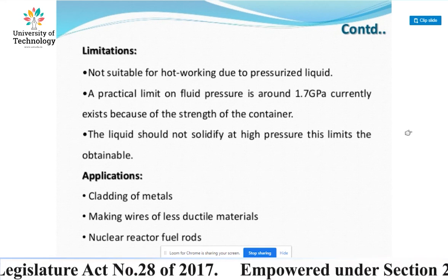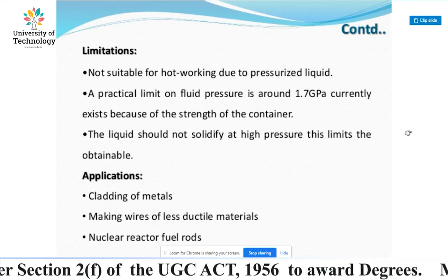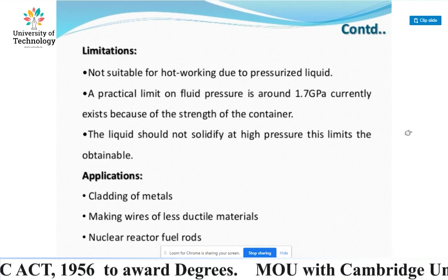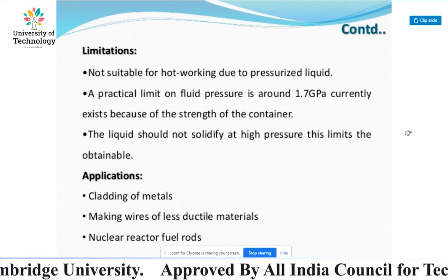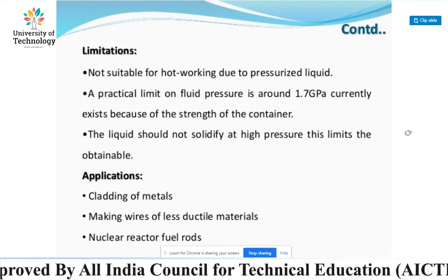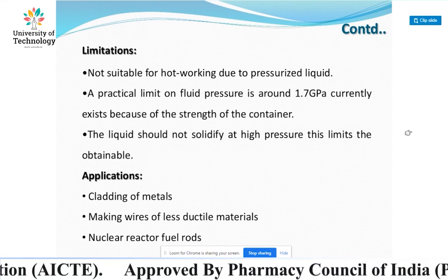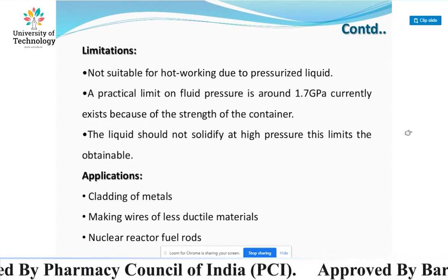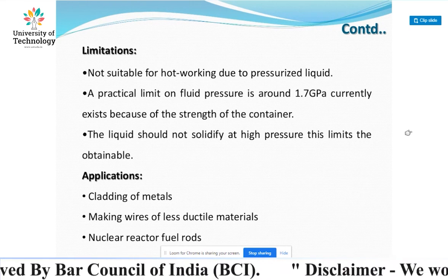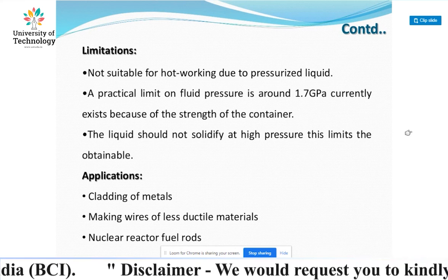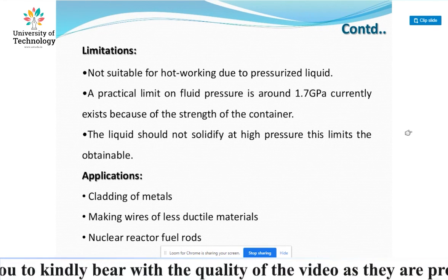A limitation of this process is that it is not suitable for hot working due to the pressurized liquid. A practical limit on fluid pressure of around 1.7 gigapascal currently exists because of the strength of the container. The liquid should not solidify at high pressure. This limits the obtainable applications of this process: the cladding of metals, making wires of less ductile materials, and nuclear reactor fuel rods. These are the applications of the hydrostatic extrusion process.